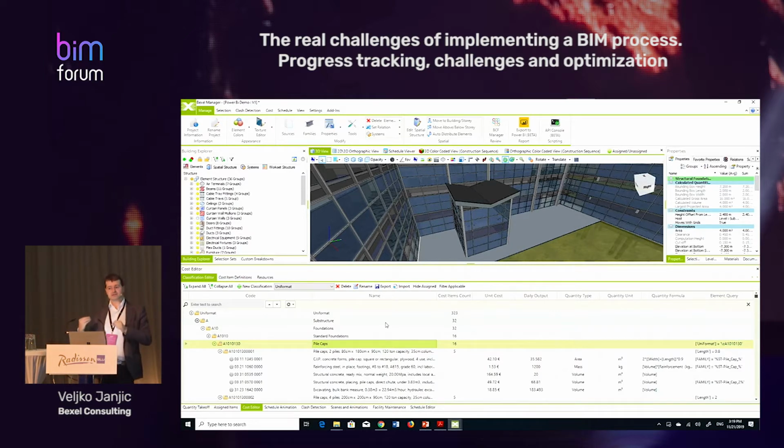And the third could be, I think there are even 4. So the elements updated in terms of geometry or just properties only. And could be a 4th one, deleted elements. So when you are updating the model, you can even keep old one, for example, to compare different cost versions or number of clashes in the previous and the new version.